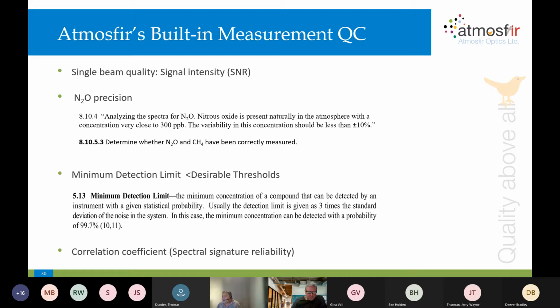In the 90s, all over the world, the concentration of nitrous oxide was around 300 ppb. Today, 20 years later, the concentration is 330, meaning that the global concentration changed by 1 ppb or less every year, meaning 0.3%. So you cannot buy a calibration gas as accurate as the nitrous oxide that God gave us.